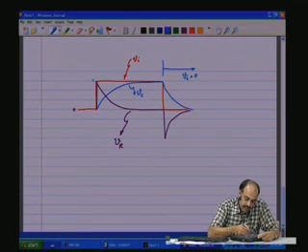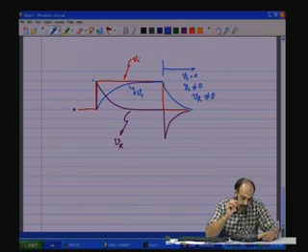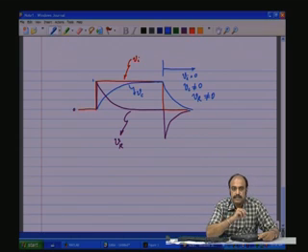So, when Vi is equal to 0, in both the cases, the Vr and the Vc voltages are non-zero. Vc is not equal to 0, Vr is not equal to 0. What does this mean? This means that the input voltage is 0, output is non-zero, therefore, the gain is infinite. So, this implies the existence of a pole.